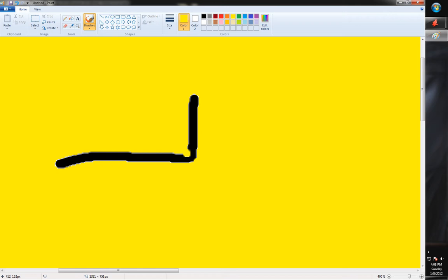So what just happened here, unknown to you, is that, well, it's probably not that bad. It's probably like that, because it etches around and up as it etches. During the etching process, all of a sudden your trace just went from 15 or 16 or 20, whatever mil width your trace is, down to really tiny right in here. If this is a high current path, let's say, you just effectively created a fuse that you didn't want in your device. Sooner or later, that's going to get hot enough because of so much current passing through such a thin trace that it's actually going to blow.